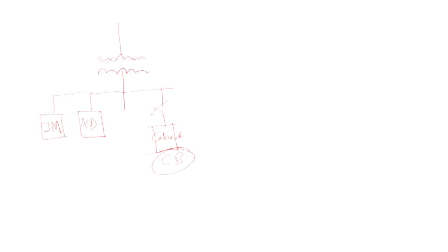Now, what happens once you close it? There is a leakage reactance of the transformer that has some value, and this capacitor you have calculated based on the power factor, since you wanted to bring the power factor to 0.95. Then what happens is that this adjustable speed drive will produce some amount of 5th, 7th, 11th and 13th harmonics, and so on.